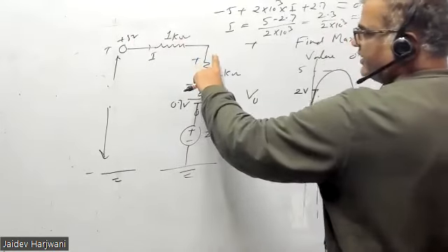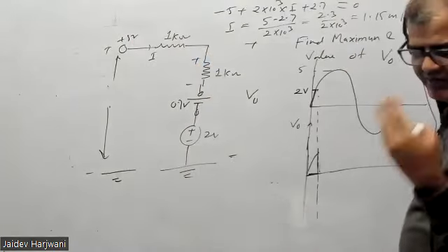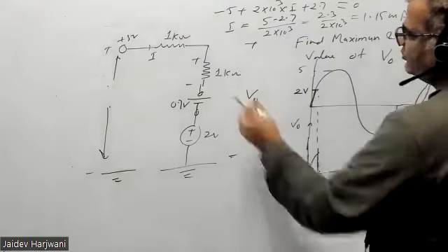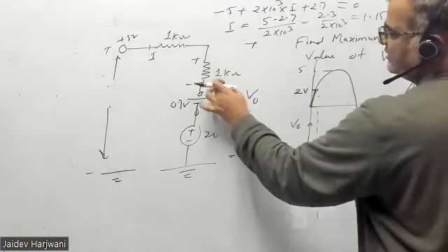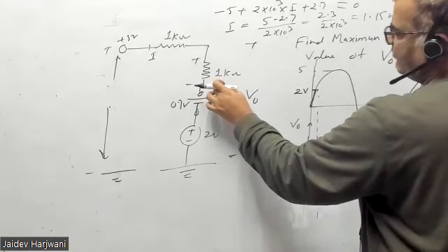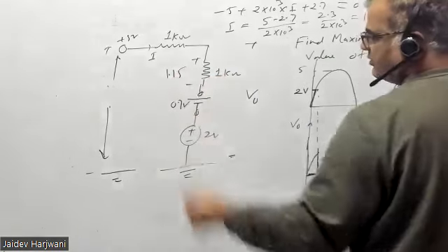So voltage will be more here. Okay, so for the positive cycle, how much is the maximum value that I'm calculating? You got the current here, this current is flowing here. So how much voltage drop will be here? 1.15, yes or no? I into R.